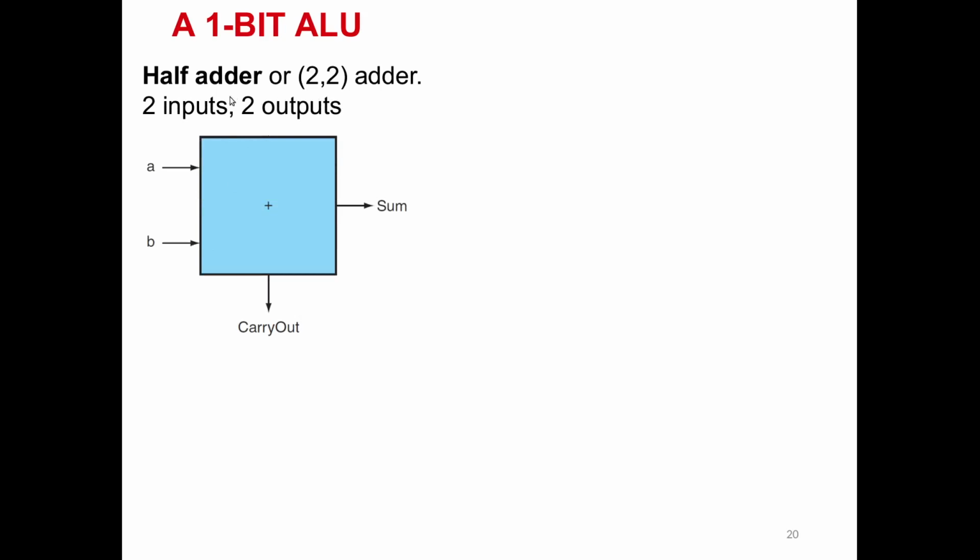We will also have the adder in order to add two values A and B together, and we have the half adder, in which, as we know before, when we add two bits together, we can have the result of 1 bit and one more carry out, or the result might be 2 bits together, and so here we have a carry out and a sum with two input bits A and B. This logic is called a half adder.